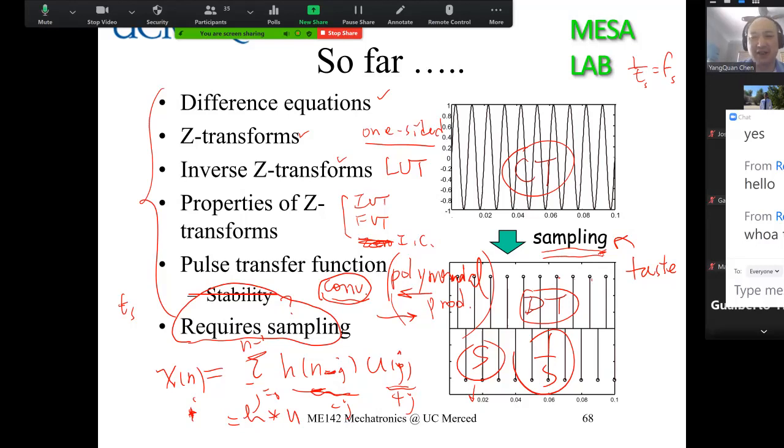So I already alerted you in the beginning. This is a very important parameter you need to decide in the early stage, the very beginning: how fast should I sample? If you sample unnecessarily fast, you pay an extra price for those high-speed sampling circuits without much actual gain.